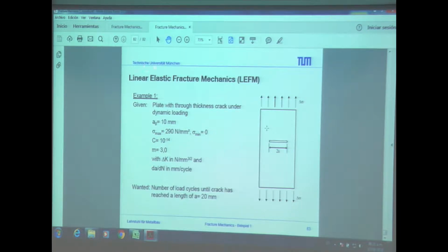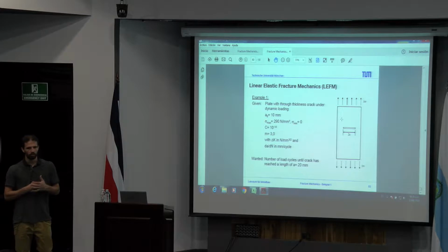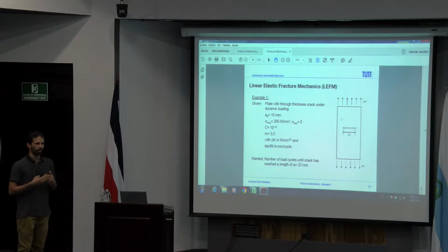If you now go for fracture mechanics, as already said, you have to calculate with a crack. This is the basic information you always have to start with. If you want to use fracture mechanics tools, you have to assume a crack, and also assume a crack length, and the size and the depth of the crack.